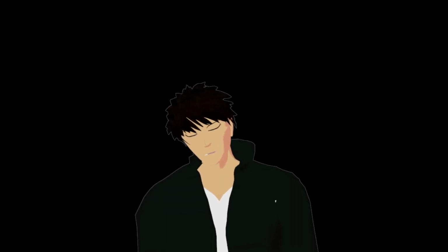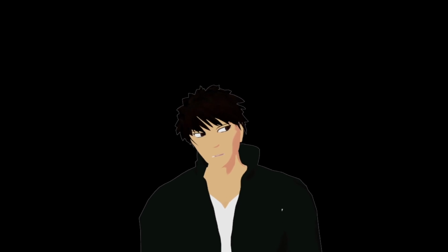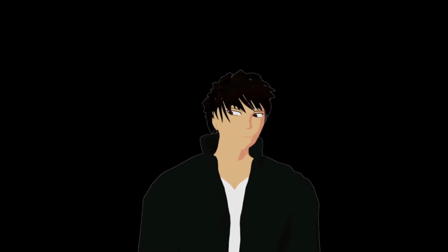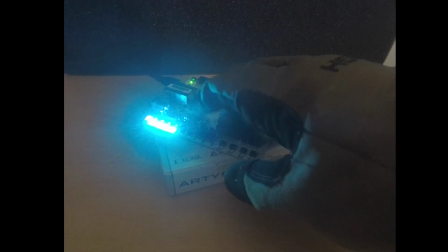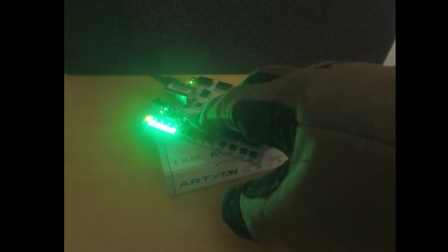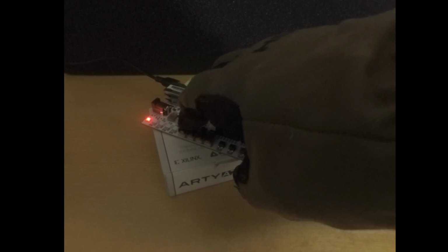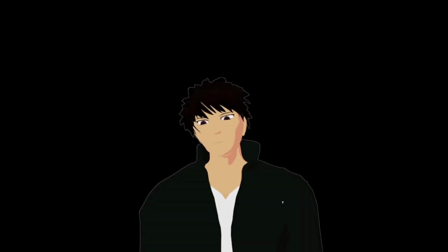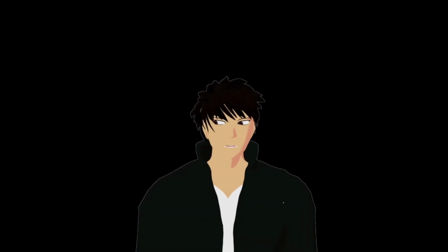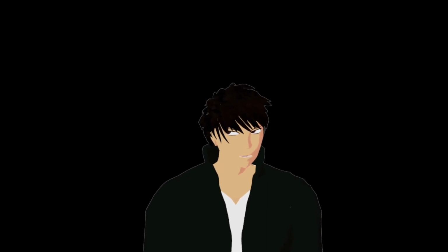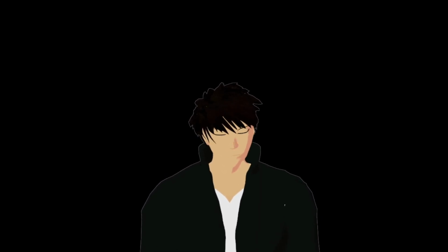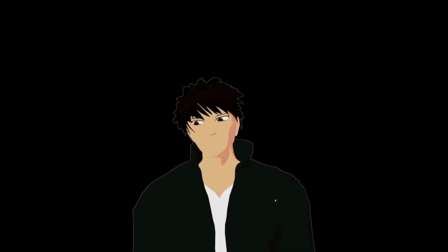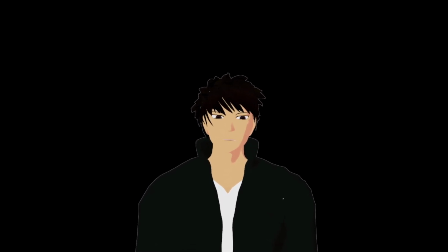And, as always, there were a bunch of dumb mistakes that took plenty of time to debug. For example, at one point the LEDs all updated simultaneously, which was confusing because the simulation all looked right. This is actually because I was incrementing the LED selector value every cycle instead of waiting for the counter to max out roughly every second. So it was rotating through the LEDs just so fast that I couldn't tell.